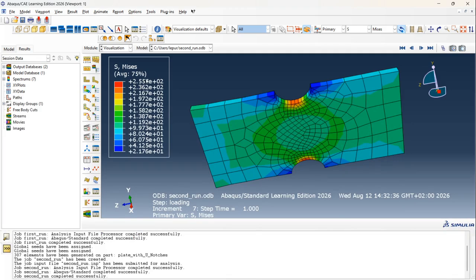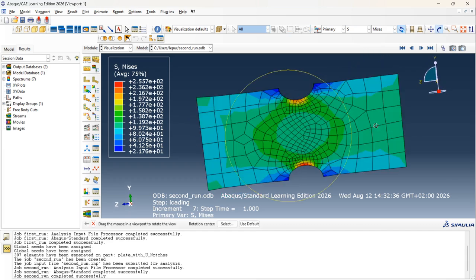So it's really better. I bet if you refine really tiny here, if we make a very fine mesh, maybe you will have the 300 megapascal here, or 269, or 259 or something. But this is fine. I just wanted to show you guys the way you compare analytical results and numerical results. So I think that helps.